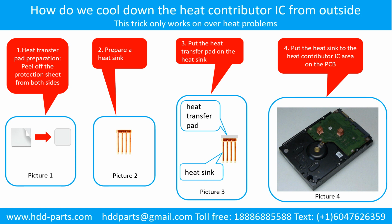Step 1. Heat transfer pad preparation. Peel off the protection sheet from both sides of the heat transfer pad, like picture 1 shows. Step 2. Prepare a heat sink, like picture 2 shows. Step 3. Put the heat transfer pad onto the heat sink, like picture 3 shows. Step 4. Put the heat sink onto the heat contributor IC area on the PCB, like picture 4 shows.